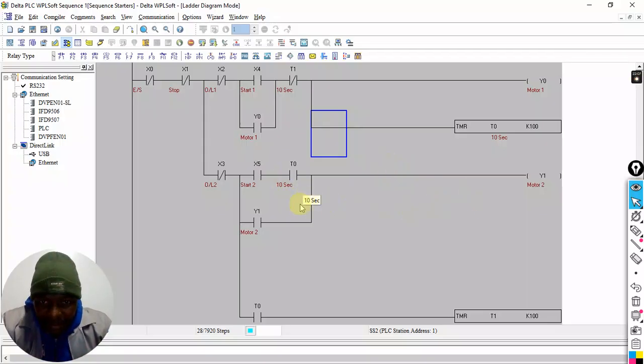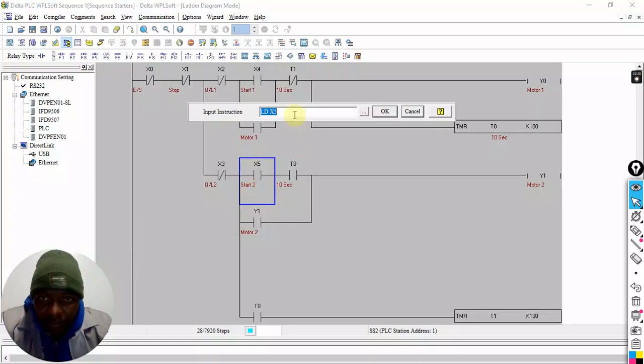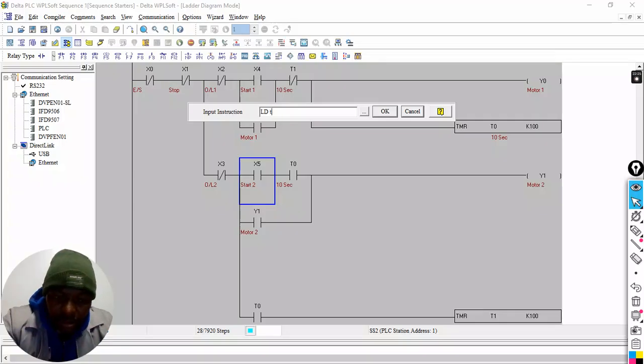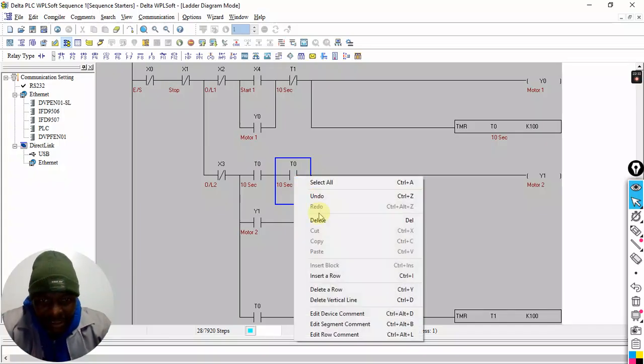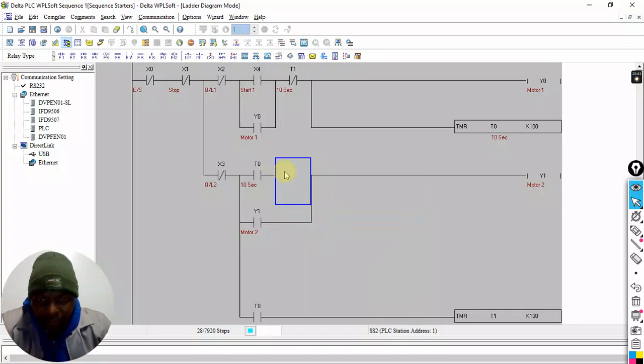I think if that was the option that they wanted, we would have seen maybe this T0. Let me rather come here and remove this. Let's change this to T0. I think you've seen the first one, you can still go back and check it. Let's change this to T0. And then let's remove this one here. I could even leave it, it doesn't really matter. It's redundant. If there are 2 of them, it just means 1. It's really an AND of the same item, basically like a buffer. But just to be safe, I'll remove that.